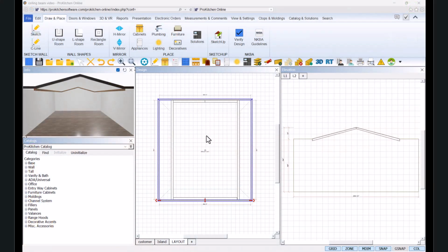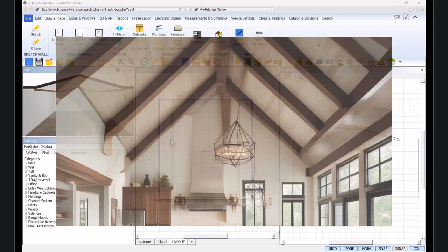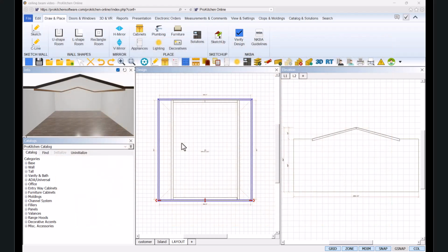But frequently, when there are angled ceiling beams used as decorative features in a room, we will see them placed along the interior depth of the space. Knowing we need to use wall user shapes to create these features, and that wall user shapes need a wall face to be adhered to, we will need to have additional walls that run horizontally along our room. Using a standard wall, however, would disrupt the visuals and create individual interior rooms.